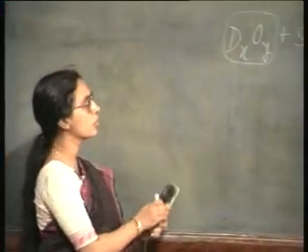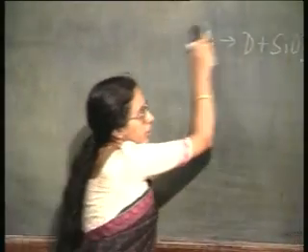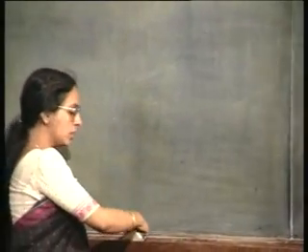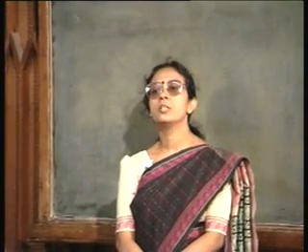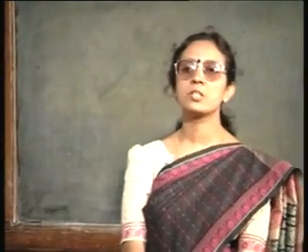Now, let us talk about one of the most important dopant materials in silicon, the only available p-type material, that is boron. In order to diffuse boron in silicon, what are the things that we should know? First of all, the diffusivity of boron, the diffusion coefficient. Now, the diffusion coefficient of boron, of any material for that matter, is going to be dependent on temperature.